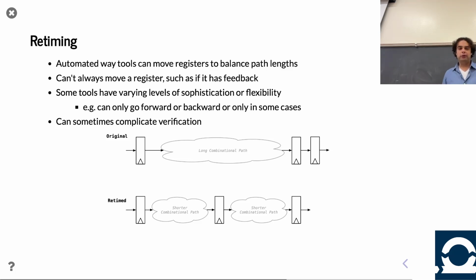And so as a designer, our goal is to enable retiming to happen. And guess what? It's as easy as just placing extra registers, making sure your CAD tool supports retiming, and tools move them forward or backwards depending on what the tools require.